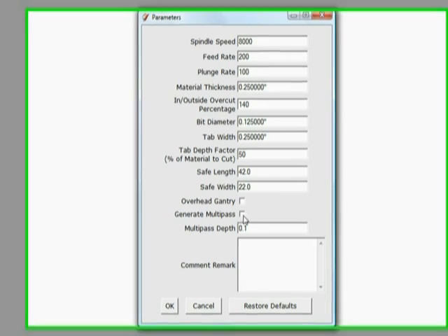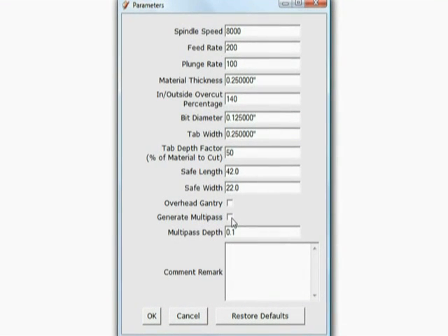Now let's say that we were dealing with a harder substrate. Maybe we wanted to use our PhlatPrinter to cut some light ply for firewalls or heavier, thicker parts. That's where this multi-pass comes in. It's going to allow us, let's say you have a PhlatPrinter MK2 that's running at easily 200 inches per minute.